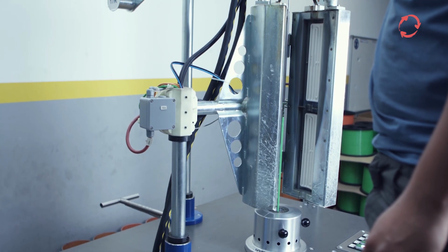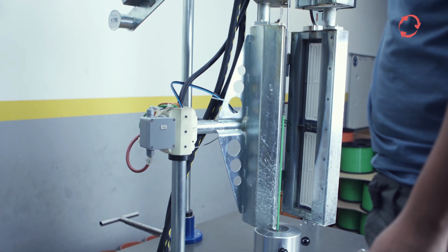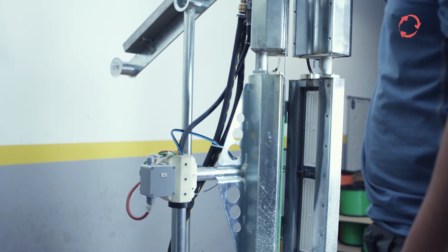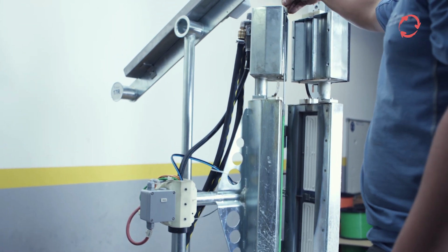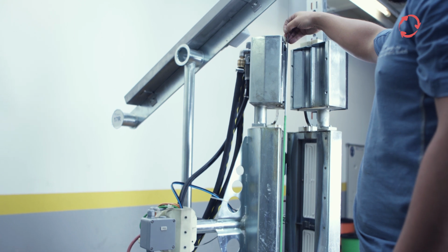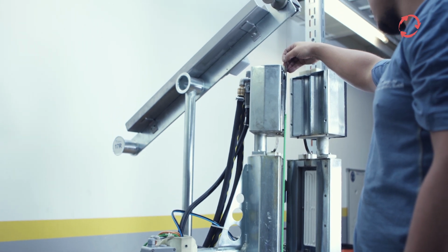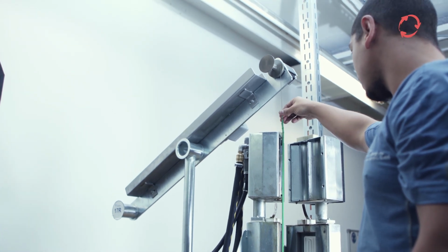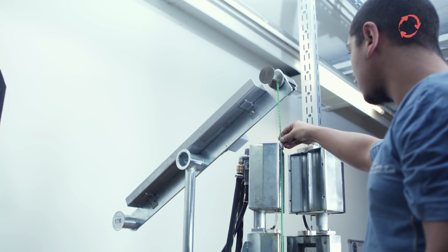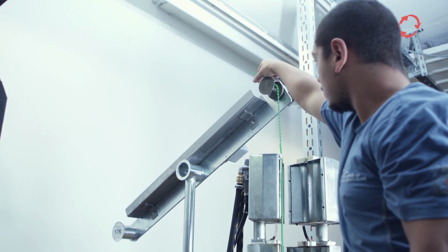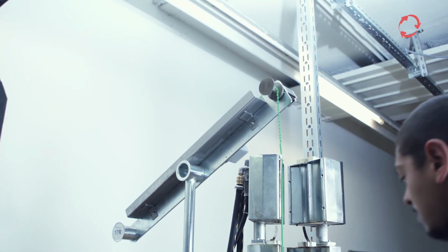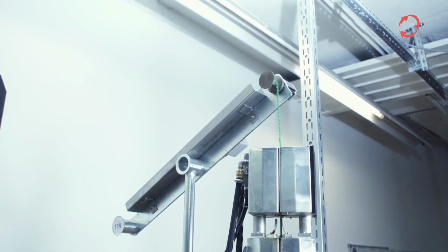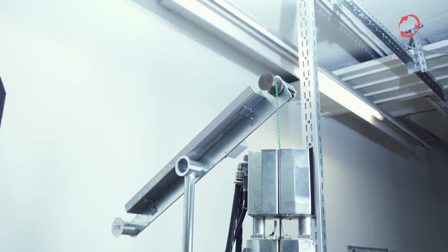During the startup phase, the wound spirals, as needed according to spiral type, must be lightly pushed up onto the mandrel by hand to avoid tangling and a resulting tear in the thread. Then the spiral must move upward on the mandrel by itself. If this is not the case, then the process parameter is not correct. As soon as the wound spiral reaches the upper end of the mandrel, it is placed on the guiding track via the pull-off roller, and the heater is closed by pressing the corresponding button once the desired speed has been reached.